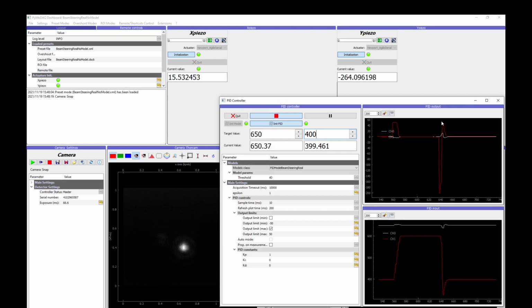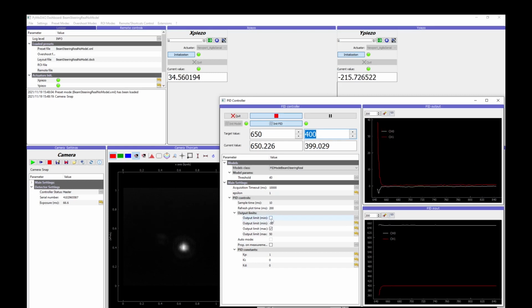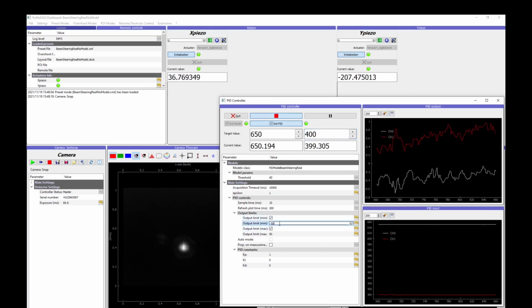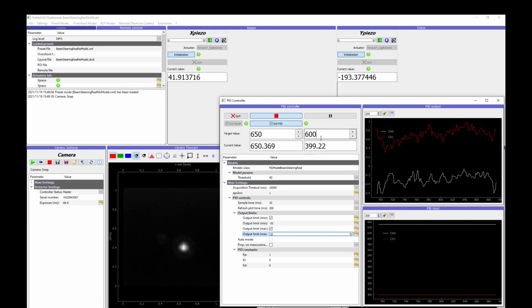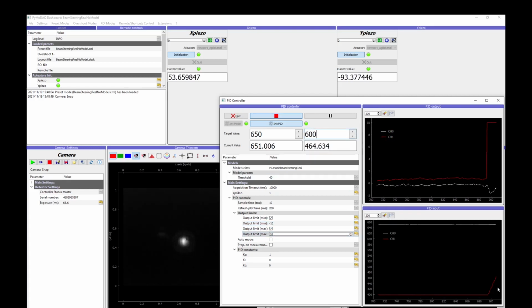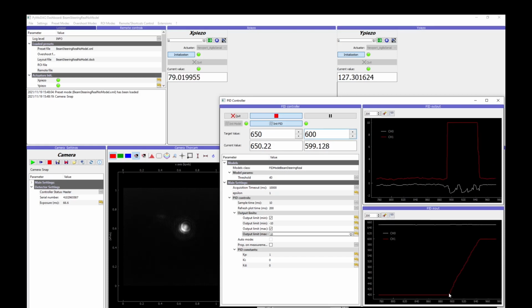And then it introduced a positive correction to correct for this overshoot. And then somehow I achieved here a 0 correction and a target position of 400. So it means that by using these outputs, I can limit the magnitude of the correction applied to my system. So I can put some very tiny numbers and look at what's happening. It's taking here forever to get to my 600 set points. But because I'm doing it, I'm also allowing my system to change only slightly at each step.